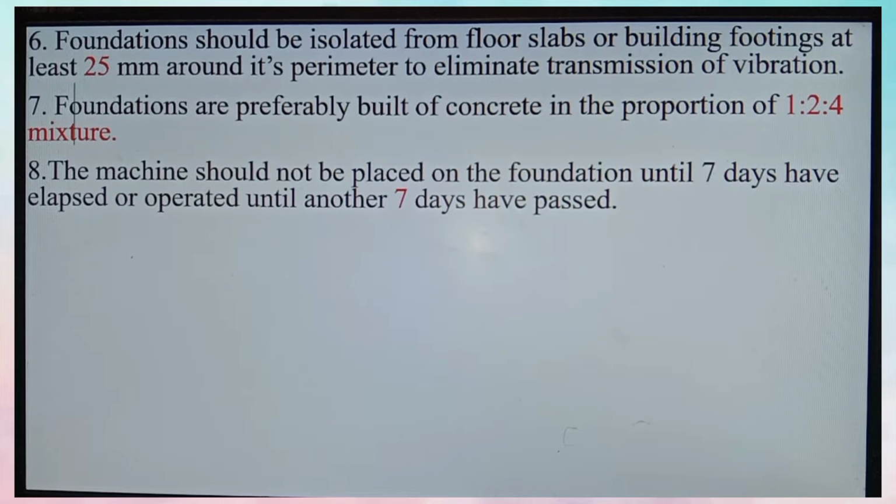Rather, the machine should not be placed on the foundation until 7 days. Why don't we want to put the machine on the foundation until 7 days? Because the preparation of the foundation is not yet hardened. The curing of the foundation is still not yet hardened.